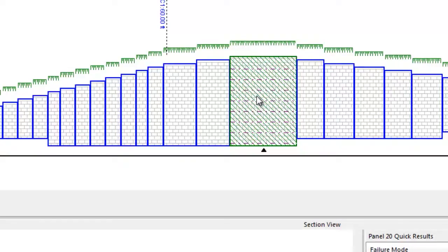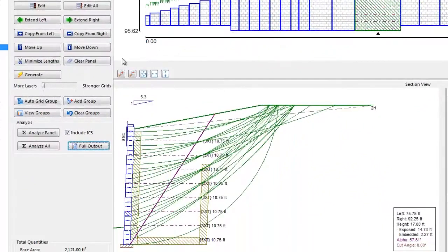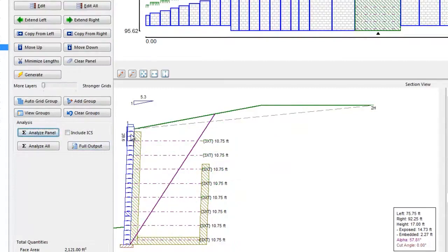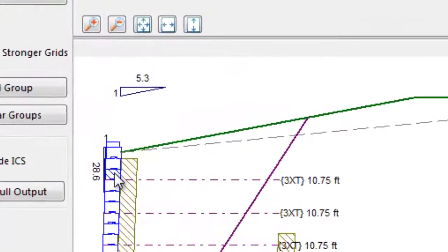When using the Generate function, sometimes a designer might prefer that the geogrid start at a specific location from the top of the wall, despite what the top overturning check might say is allowable. Perhaps her experience has shown that it is prudent to have no more than, say, 2 blocks unreinforced at the top of the wall.